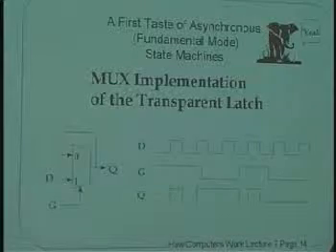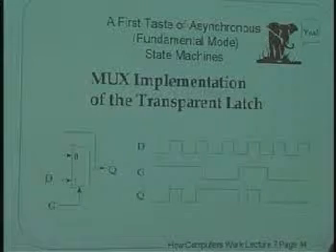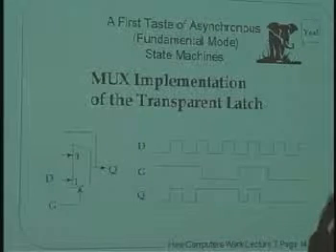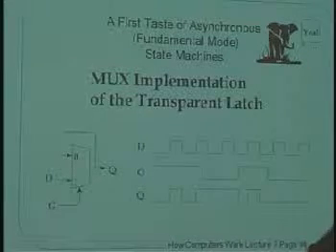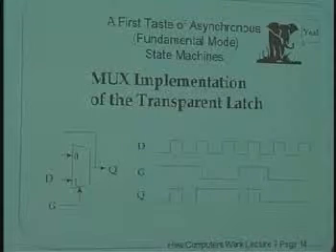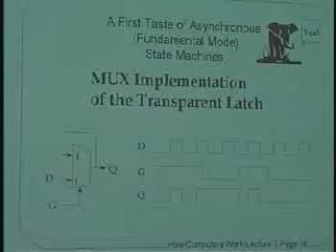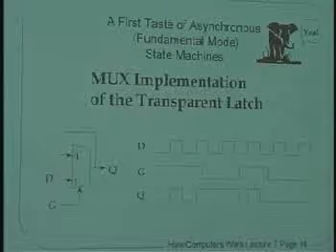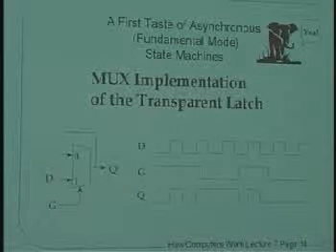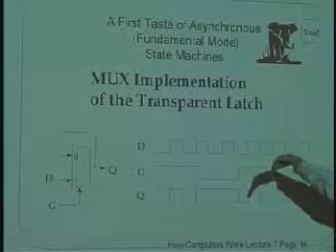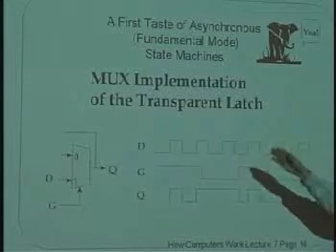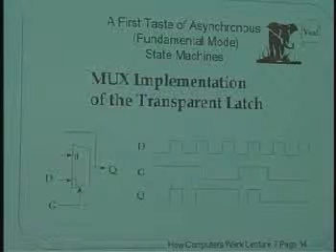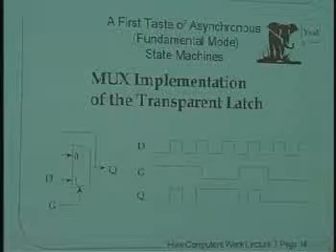Now, what does G stand for? G stands for gate. It opens the gate, the data flows through the window. Close the gate, and it holds on to the stuff. Okay? So it's an amazing circuit. It's an amazing circuit because it can remember stuff. After we have switched G from high to low, we don't care what D is anymore. It remembers this old value of D, which was present at the instant when we closed the gate.